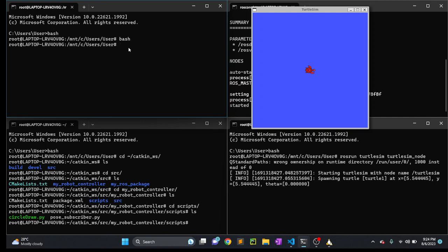Here I am going to fetch the important information about the subscriber node, and first of all the publisher node. For fetching info I need to type rostopic list to check what is available here, and you can see the turtle1/cmd_vel topic, this is our publisher topic.